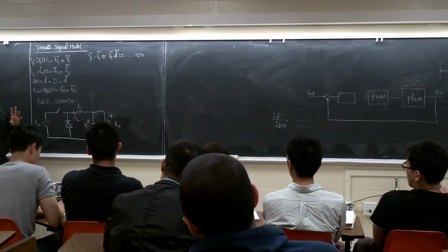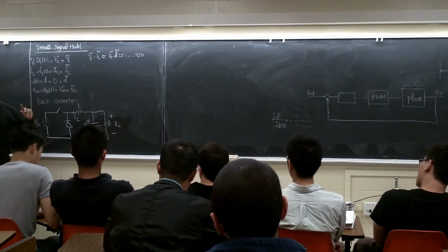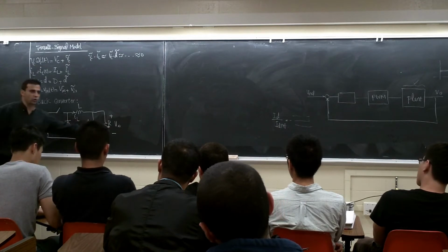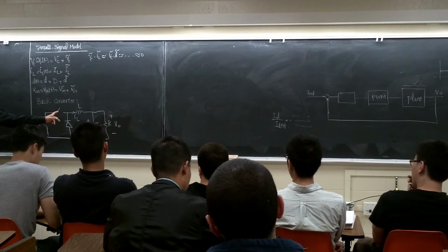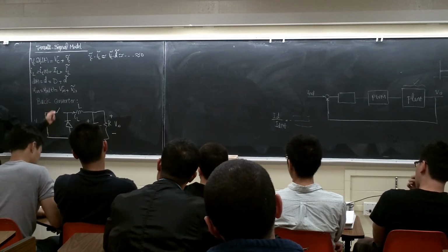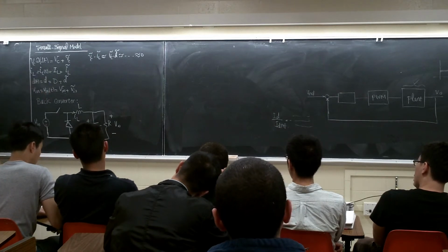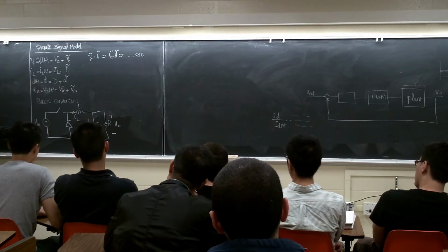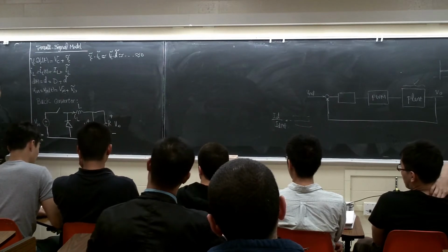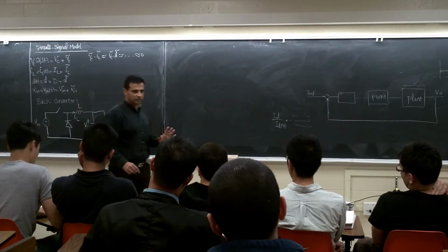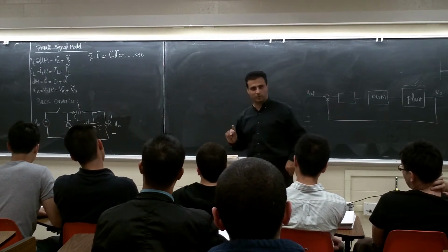Let's say the parameters under my control are those I can change to control the VO. What are those parameters? One is the duty cycle of this switch; I can change this duty cycle to control this VO. And what else? V in. I'll put V in for now as a variable, but usually V in is constant. Let's start with a variable to get the equation together, but after that I'll say V in tilde is zero and get rid of that one.